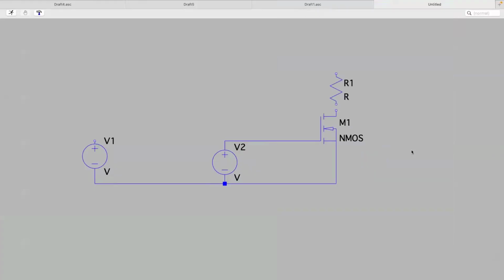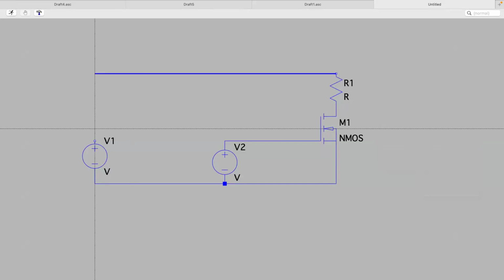Anyways, you can't rely on it, but in LTSpice, I think all of the MOSFETs don't have that diode. I might be wrong on that. Anyways, let's add the wires for the drain of the MOSFET and the voltage source.